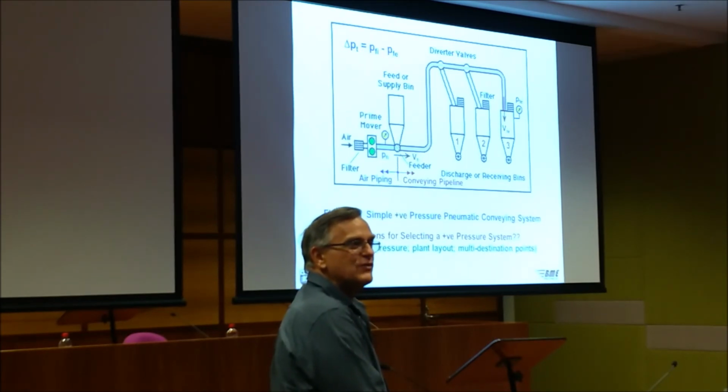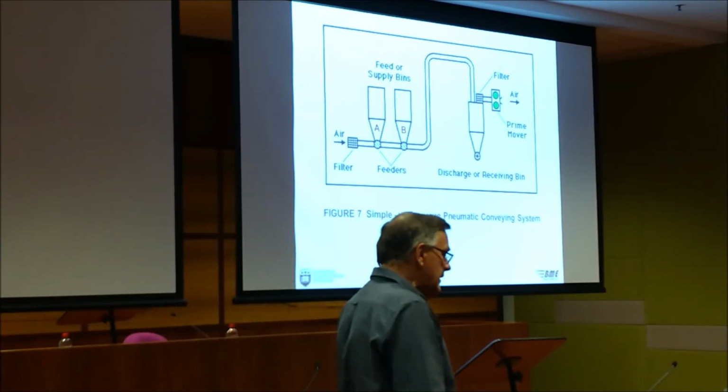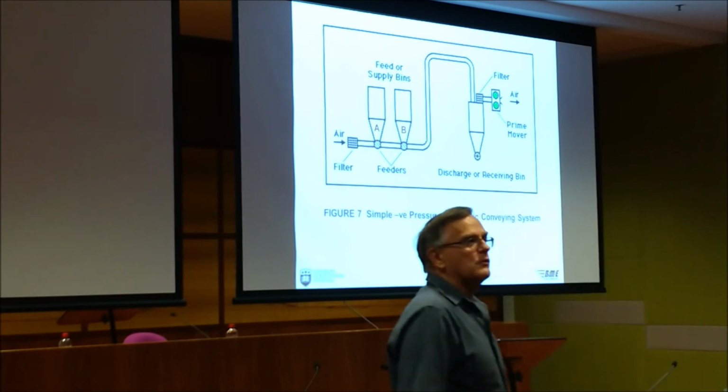So a few little things to remember about pneumatic conveying. Velocity always increases in the direction of flow. As a result, it's the last bend that will wear out first.